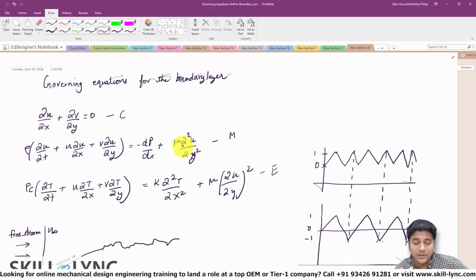But as we have been seeing so far, we have always used a turbulence model, right? So whenever we set up the shock flow problem or the conjugate heat transfer problem, we always used a turbulence model. Why is that? Well, if you look at these three equations, if you solve them, they are completely capable of giving you solutions for both laminar and turbulent flows. And if you do that, then people would say that you're performing a direct numerical simulation.